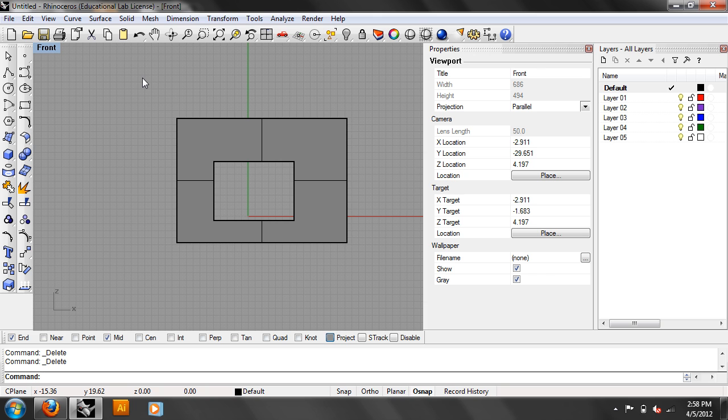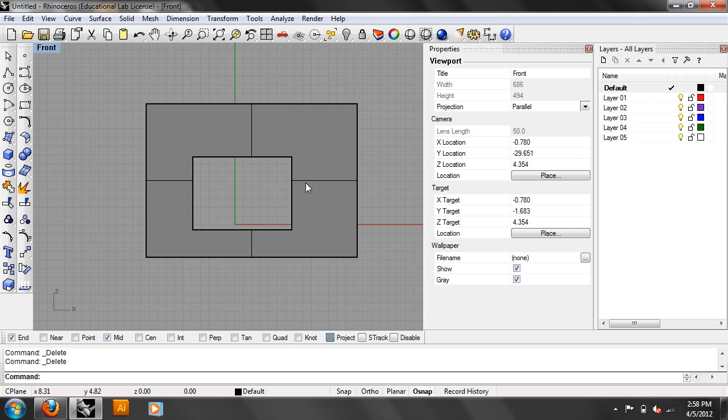With that mullion, in this case say it's a window like that, would you give that a thickness versus the curtain wall mullion? Oh, would you give it a thickness? Yeah, you still give it a minor thickness. I don't give glass thickness because I don't need the physical properties of glass. All I care is that there's the transparent material. But with a mullion, it's going to cast a shadow, and if you cut a section of it, it pays to make it real.